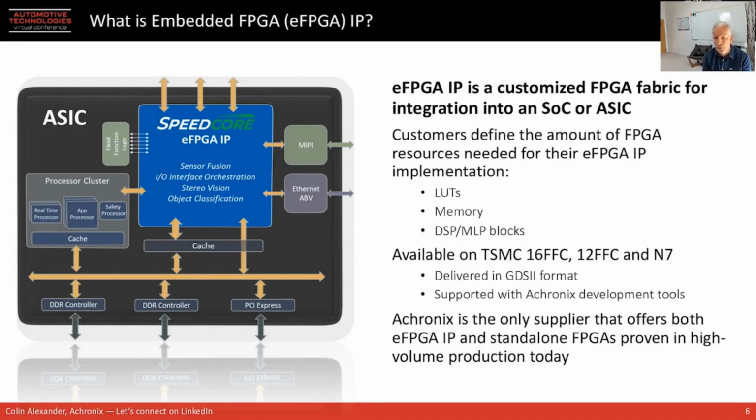We have what we call the 2D NoC that provides a high bandwidth connectivity between the heterogeneous functions on the SoC, CPUs, peripherals, memory, and I/O, together with the fabric. This interconnect enables a number of very important benefits in optimizing designs and supports the ability to dynamically reconfigure the fabric in real time. The mix of functions on the SoC can support multiple capabilities that ensure resources perfectly match the requirements of the emerging ADAS requirements.